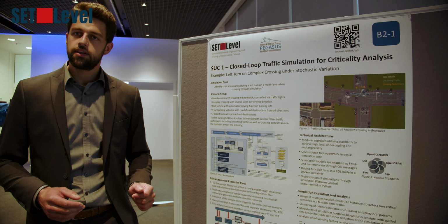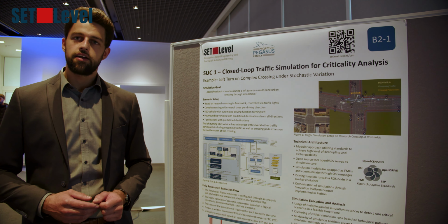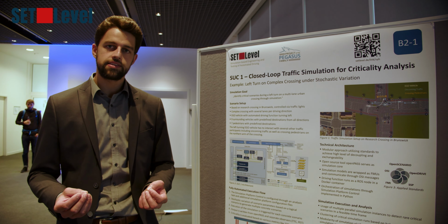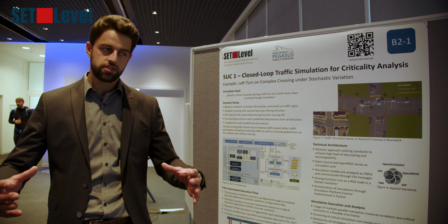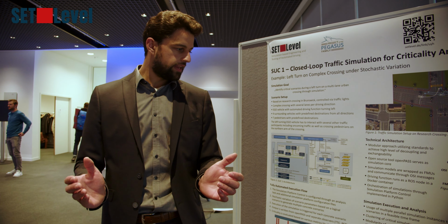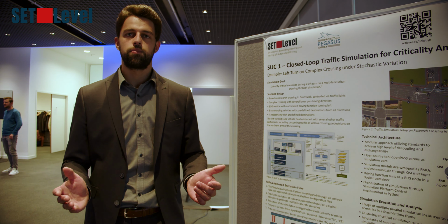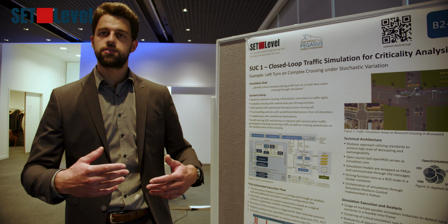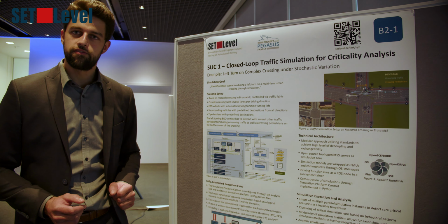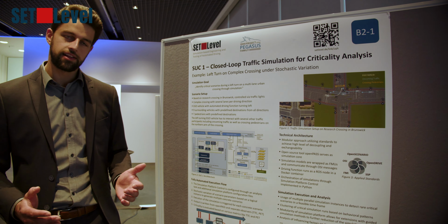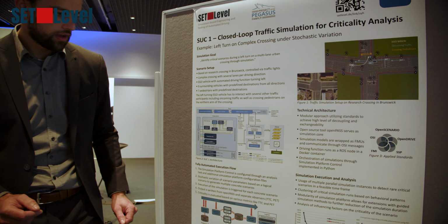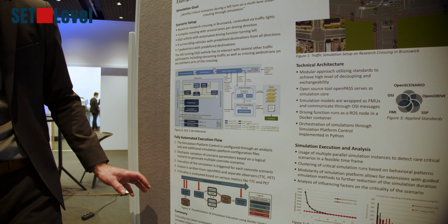Now, I've already pointed out FMI as an important standard. I've pointed out OSI as an important standard for the communication between different simulation models. I've pointed out SSP, which we use to combine several FMUs in a larger network for the ego vehicle. And of course, we also used OpenDrive and OpenScenario to define the map and also the dynamic behavior in our simulation. After we have built up all of this and integrated it from the technical point of view, we were able to execute the simulation, which is shown in the bottom of the poster.